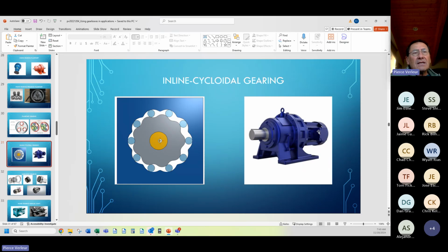At zero velocity, I'm going to measure the deflection of the input shaft. If it's zero, it's super stiff. The deflection in arc seconds, let me back that up again. The deflection on the output with this torque arm, with the input shaft held fixed with the brake, is your deflection and your measurement of your stiffness.